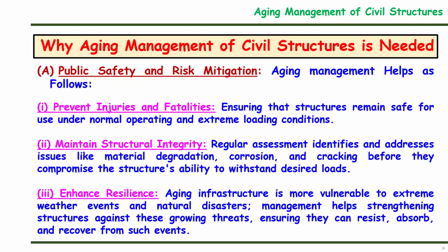And if we carry out regular assessment, that will help in identifying and addressing various issues like material degradation and corrosion of reinforcement, particularly cracking in RCC structures, before the capacity of the structure is compromised to withstand the desired load. This is our main criterion.